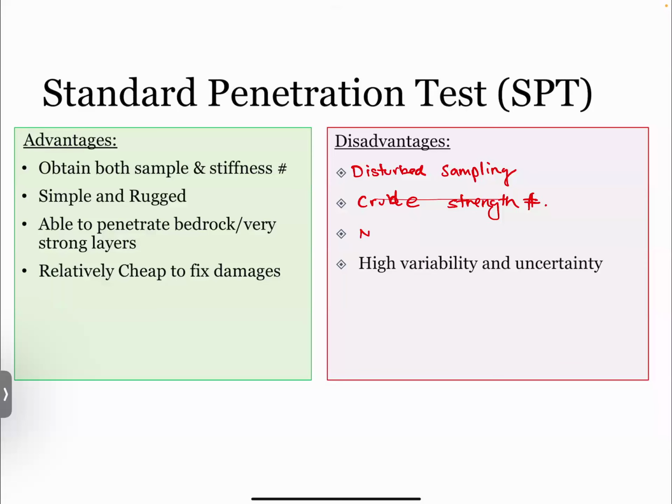Which means it's not always applicable to fine-grained soil. So really understanding what the potential strengths are of our soil. If it's clay and it's very sensitive and, quote unquote, weak or soft clay, then doing this test, it's not sensitive enough to actually measure the strength or the stiffness. You're just hitting it with a hammer and saying, oh, there's zero strength. It's like, no, there's still strength there. Your equipment is just not sensitive enough to measure it.